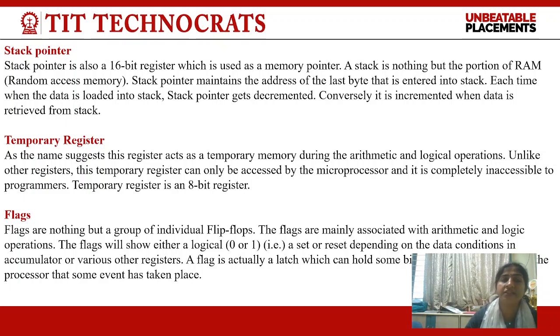Now, the next is the temporary register. When an arithmetic or logical operation is going to take place in the ALU, the first 8-bit data is going to be attained by the accumulator, and the next 8-bit data is going to be attained by the temporary register.